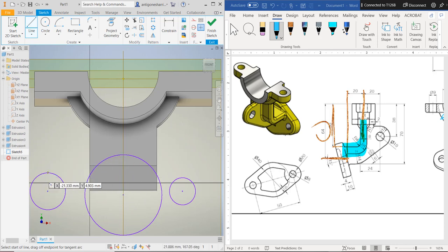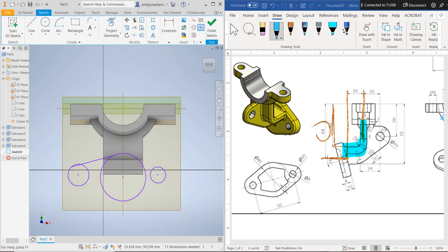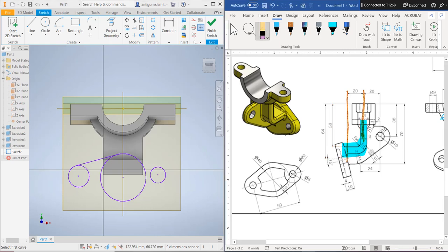I showed you tangent already, so if I pick these two objects, just make sure not to pick them exactly at center. I can go to my constrain tangent and say, I want you to be tangent to you. I want you to be tangent to you. Got it? That's how that works. The rest you're going to build yourself. You're going to say, where do I exactly position this? That information is right there for you. Your position is 64 vertically from the top. Okay, 64 vertically from the top.